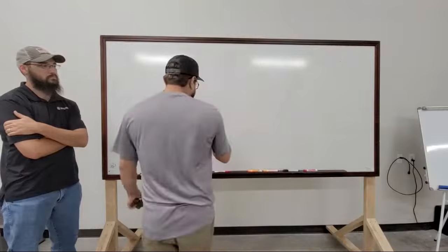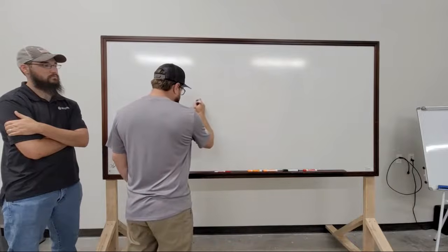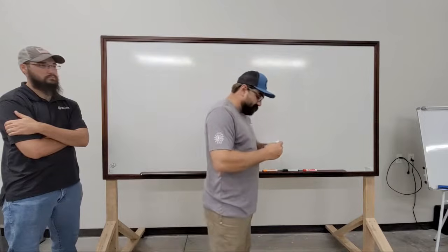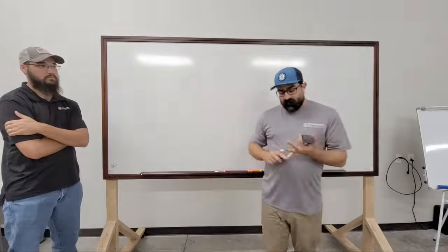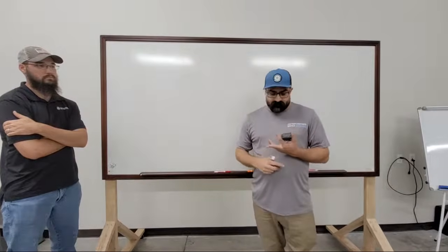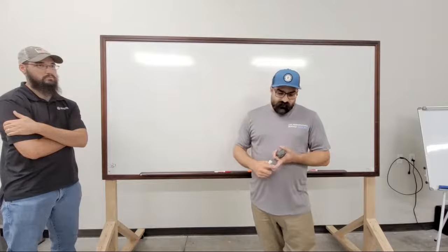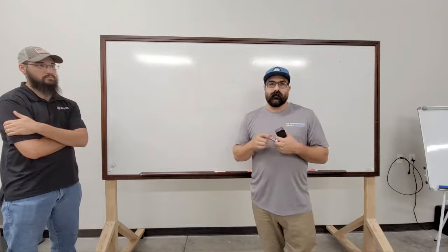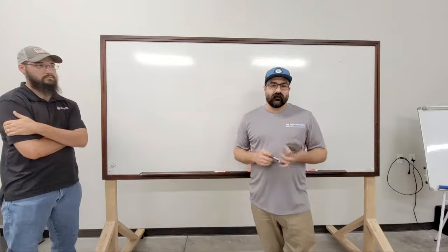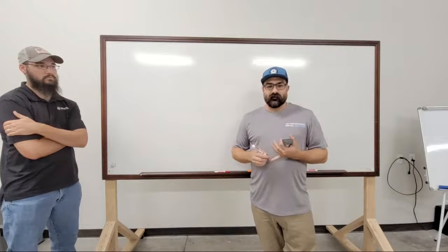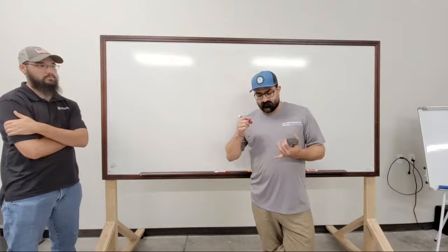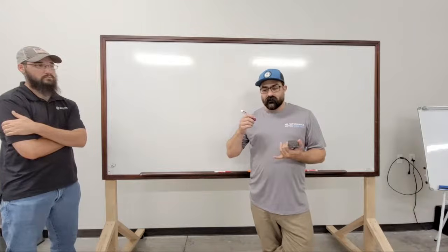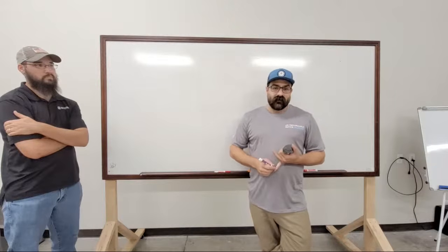There are two types of fan power terminals. Oh, that's something we can touch on first: FPB, FPT, FTP, VAV. A lot of these nomenclatures are synonymous with each other. Basically, if somebody says VAV, they can be talking about something with a fan in it, or something without a fan in it.